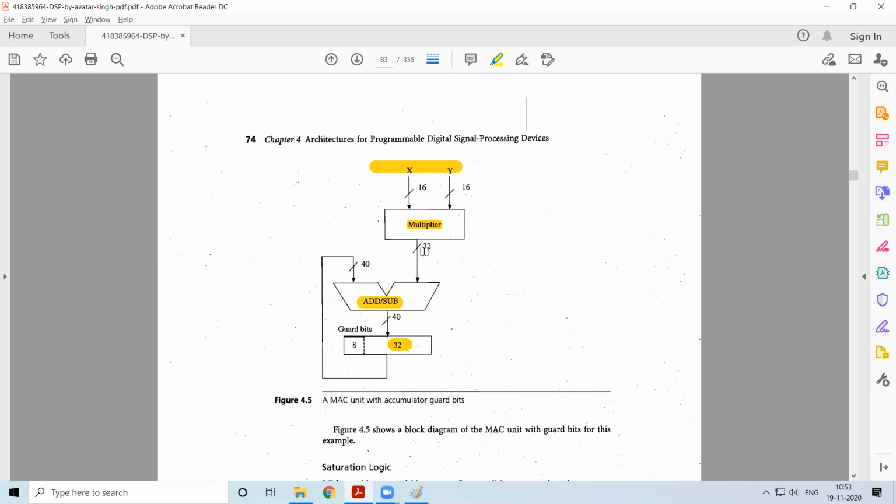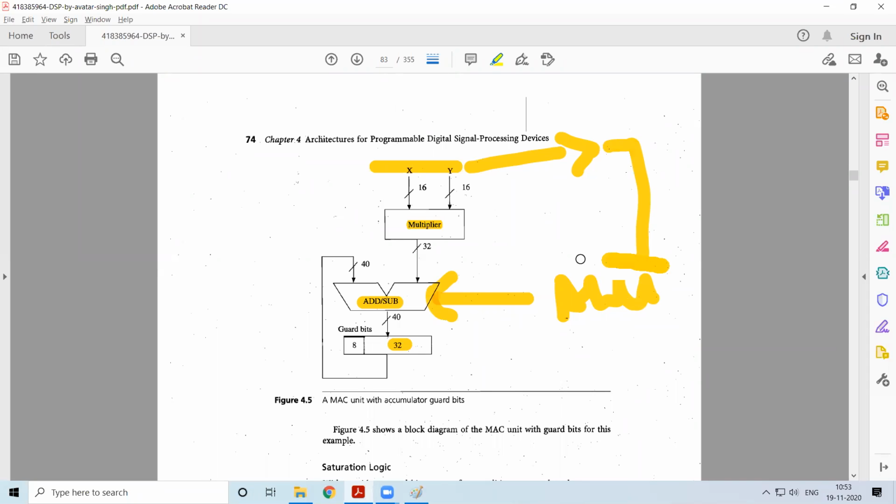In performing this, you're adding and subtracting, which is performed by your arithmetic and logic unit. Now, in order to calculate the address of the next operand, you should also perform some mathematical operations. Again, you might add or subtract. If they're stored in one sequence, you keep on adding to the address of the previous operand and keep on fetching them. This also goes to the ALU. Now the ALU is kept busy over here.